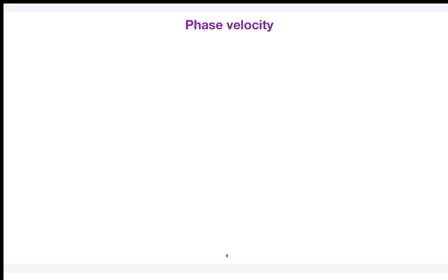So you are going to get the phase velocity is equal to c by root over 1 minus (fc by f) whole square. So here you have to notice one point. If you want to expect any propagation in the waveguide, your operating frequency should be higher than cutoff frequency. In that case, what will happen? If your frequency is greater than the cutoff frequency, in the denominator, you are going to get less than 1.